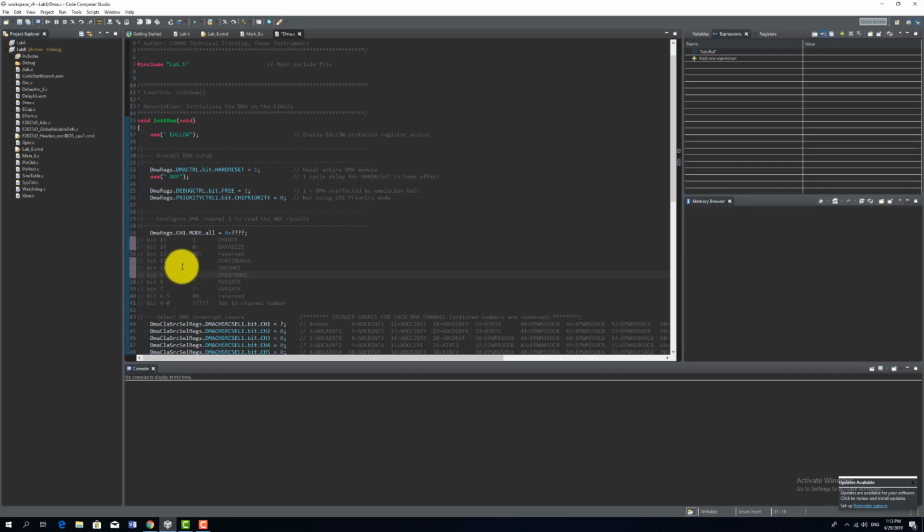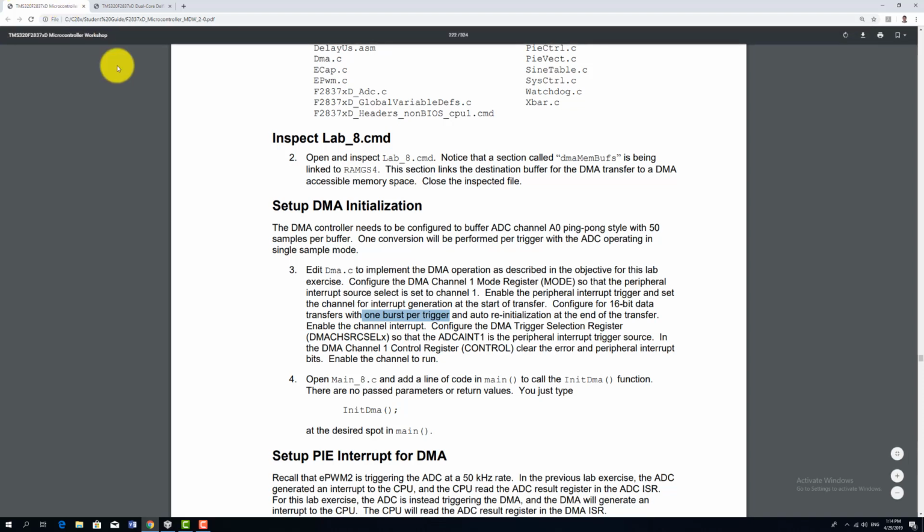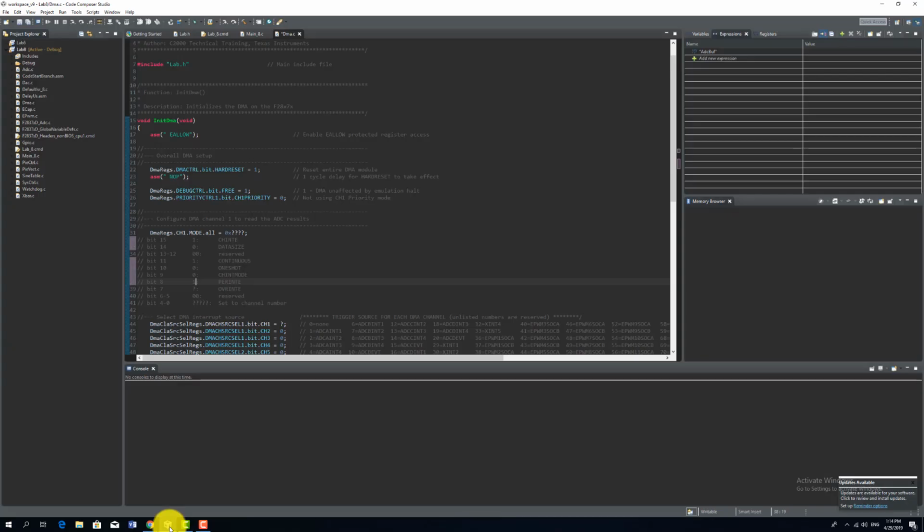Next bit is the bit number 8, involves the peripheral interrupt enable. Since we are dealing with interrupt and we want to enable, just simply put equal to 1, 0 for disable. So for the overflow interrupt enable, as we notice on the procedures, there's no such thing as overflow flag, meaning if there's no condition written in the procedure, we have to assume that the value is in its reset mode. The reset mode always for any of this field is always equal to 0. Therefore, we have to put here equal to 0. The next bit, 6 and 5, are reserved. So let's skip this, 0, 0.